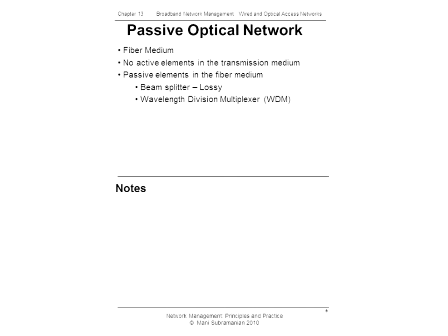Optical access networks basically use optical fiber transmission from the central office to the customer premises. And the transmission path could have active elements such as regenerative repeaters or amplifiers. Passive elements such as a beam splitter or a wavelength division multiplexer, that is WDM, could be present in passive optical networks.